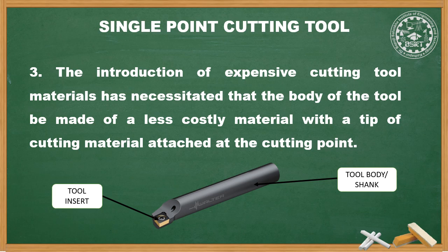There are different shapes of inserts, and they can be bolted or riveted at the time of performing the cutting operation. The tip or cutting insert is held in proper position mechanically or permanently soldered or brazed in position. It may be pre-sharpened, or it can also be sharpened using a grinding machine.